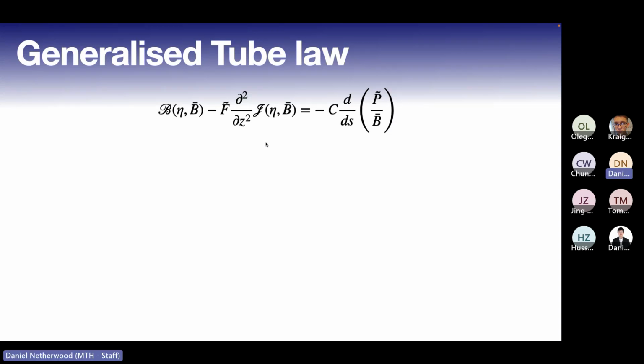Once you've done that, you then have an opportunity to construct something known as a tube law. A tube law is the overall goal of what we're trying to deduce today. It is a functional relationship between the pressure, the thing that deforms your tube, and the change in cross-sectional area. If you have that, then you have a good model for your wall mechanics that you could then use robustly to couple fluids and solids, which again is the global goal of what I'm doing here.